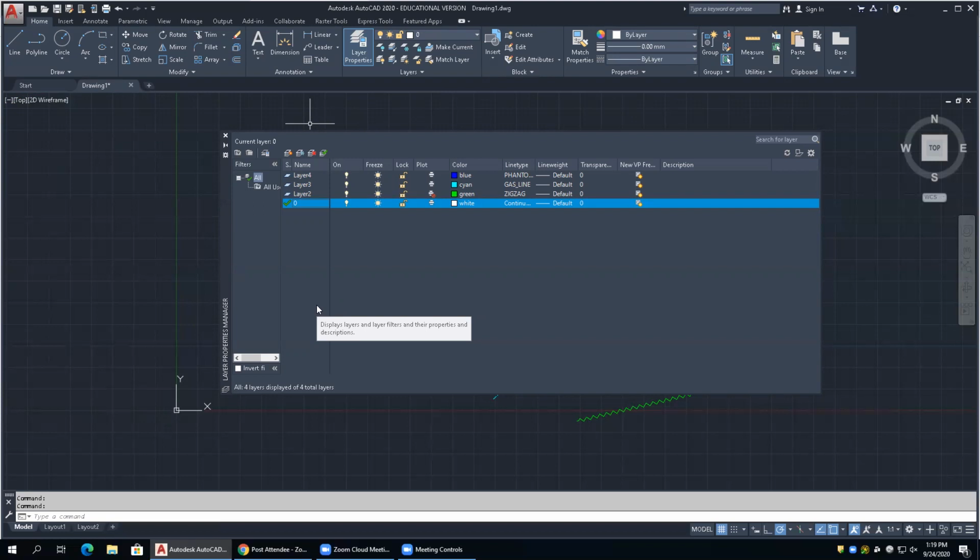The current layer. See that you got some unlocked. So see the locked ones. You might want to, no, you're locking them. Unlock them. There you go. Now you can manipulate things. If you were trying to delete things before, it wouldn't have let you because they were locked. Oh, that might have been your issue. I'm almost going to guess that was your issue. Let me know. Okay. Anything anybody can think of?